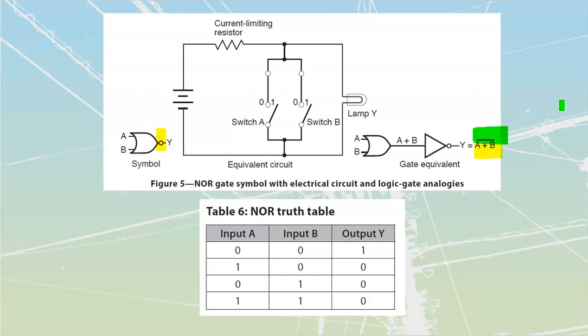I don't know if you remember what the expression was for an OR gate. It was that any high gives a high. In this case, now that we're at a NOR gate, we are going to flip that expression around, and we're going to say that any high gives a low now. In other words, if I look at my inputs over here, if any of these is high, I'm going to get lows out of this over here.